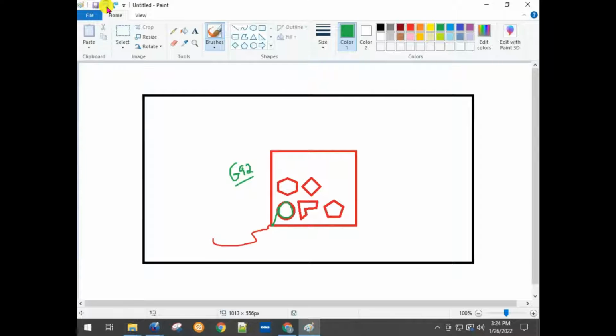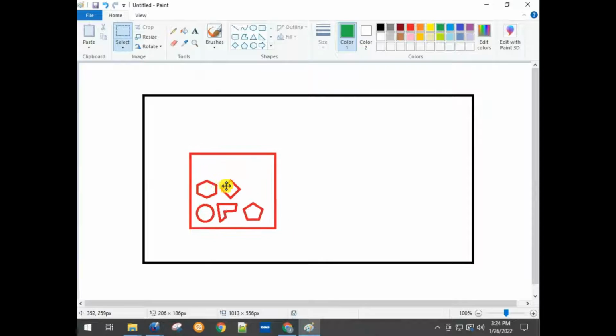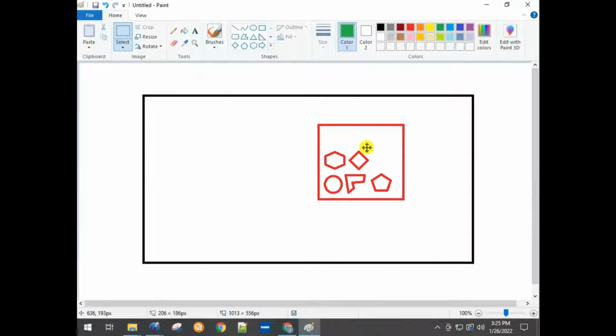We also have the ability to use work offsets. What that does is help people who do repetitive work, cutting this CNC file 100 times a day, every day, or maybe the nest might change but the sheet of material is the same, and they always want to cut it in the same position on the table every time.